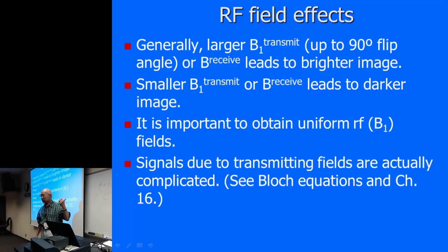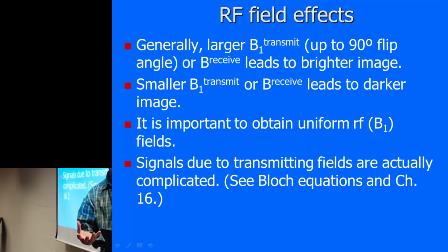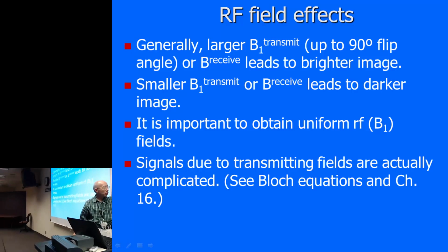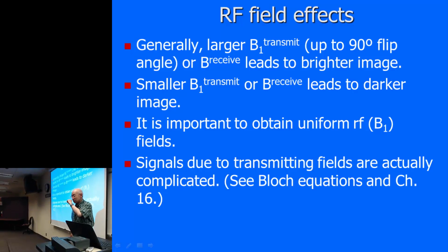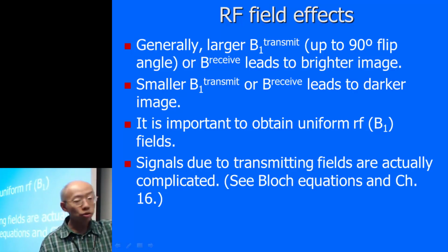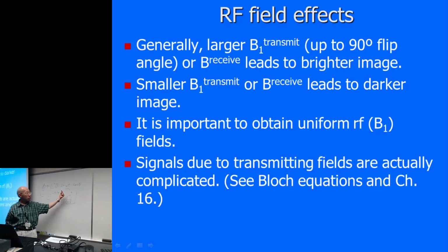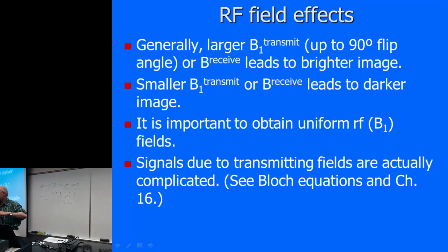Okay, so it really took some genius to design that birdcage coil such that if you take the Maxwell equations and do the calculation, meaning that if you have a sufficient number of what we call the legs in this birdcage coil, you will discover that it will produce a uniform B1 field inside this coil, and when you impose this sine omega t distribution of the field, then this field becomes a quadrature field, meaning that you will rotate, precess, inside the bore of this coil.